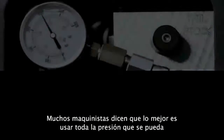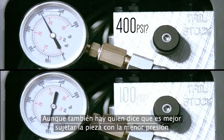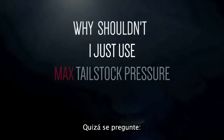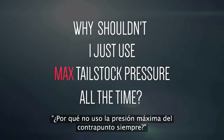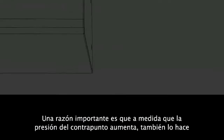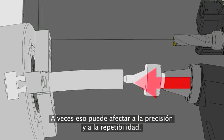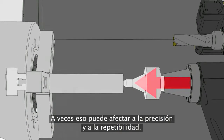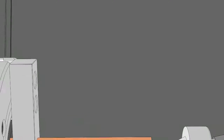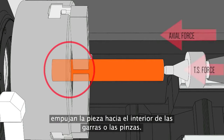Many machinists believe it's best to use as much tailstock pressure as possible so the part doesn't come out. Others believe you should hold your part with as little pressure as possible so you don't deform your part. You might be thinking, well, why shouldn't I just use max tailstock pressure all the time? Well, one important reason is, as tailstock pressure increases, deflection in the workpiece and in the machine also increases. Sometimes this can affect accuracy and repeatability. You can also increase wear on your live center, and now you're adding more force to the already existing axial cutting forces, which are trying to push the part inward past your jaws or collet.